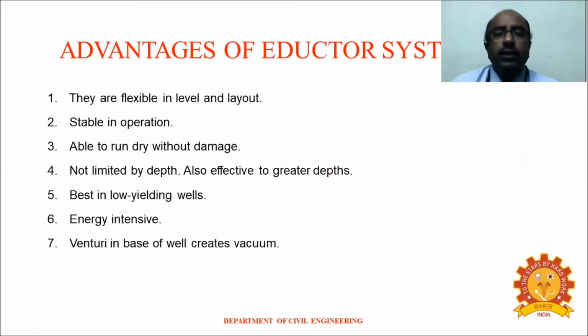Now, what are the advantages of this eductor system or jet ejector system? They are very flexible in level and layout, so we can put them at any point, and it is stable in operation, and it is able to run dry without damage.